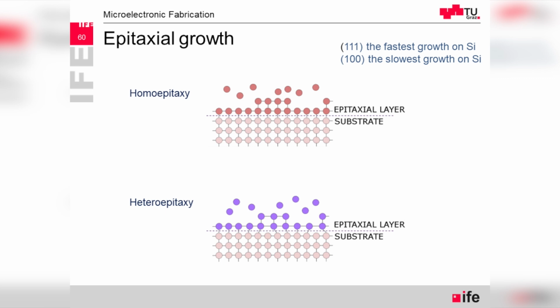But normally it's also a challenge to deal with these additional stresses. So one more feature for epitaxial growth, as I have highlighted with some other processing steps, the crystallographic orientation. The speed of the epitaxial growth will be different depending on the orientation, because also the number of bonds per unit area depends on the orientation. So that's the simple generalized relation.